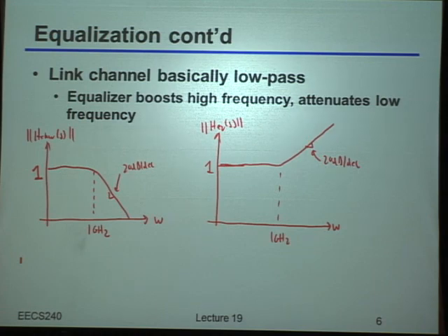Okay, great. So the first thing you can do, which hopefully should be obvious, is nobody said this has to be actually 1. I can take the whole thing and scale it by some arbitrary constant. And to zero order, nothing really changes other than just the magnitude of the signal coming out of the equalizer. That certainly works. There's no problem with that. There's another thing that I will claim we'll actually have to change in order to make this work. So what's the problem? Okay, there is indeed normally delay through that. Let's not worry about that so much.